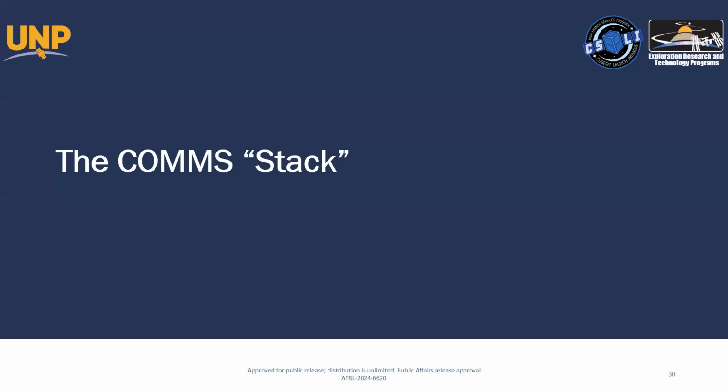So the comm stack. This is a section that's important, but it's not critical. The reason I'm telling you this is so you're cognizant of how the underlying communication works. When you see things like, oh, this uses QPSK with a 1/2 BCH coding, what does that mean? Why should I care? This is all stuff that you need to at least be cognizant of, because it will change the characteristics of your radio, as well as those system design pieces we talked about: how long it'll take to develop software, whether or not you can close the link. All that depends on what we call the comm stack.